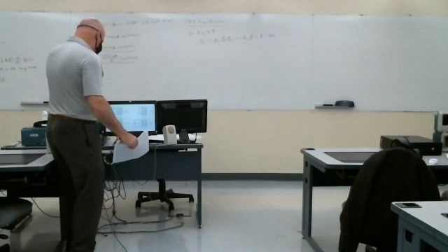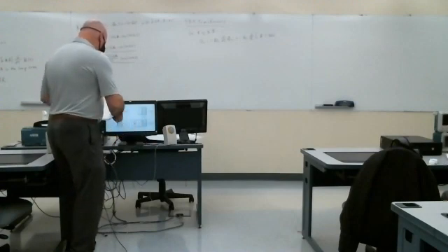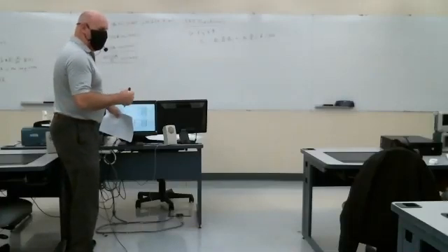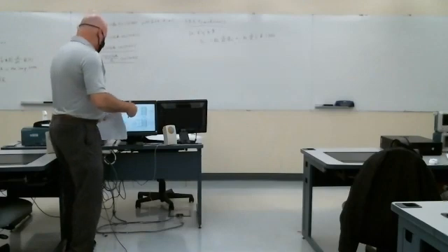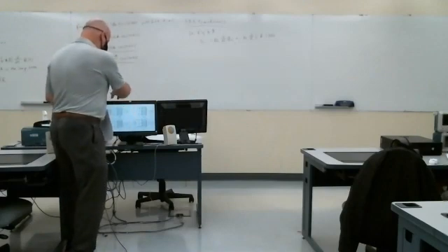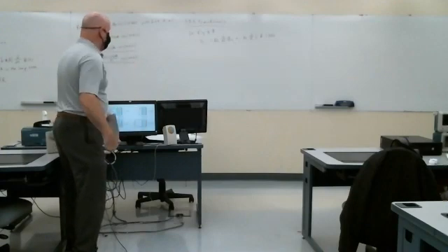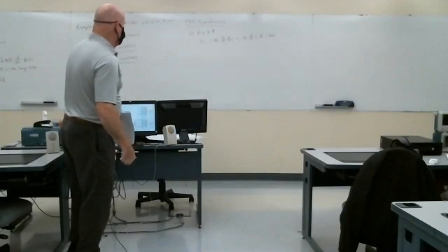If you look closely then at the other coil, assuming V1 is positive, now we treat that other coil as a load. So current would be flowing into the top terminal, and then the flux would be negative Z directed in that case.